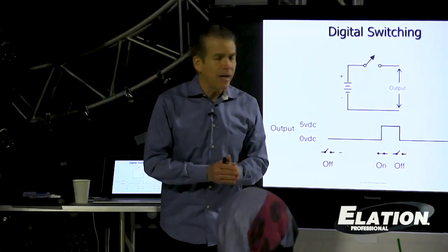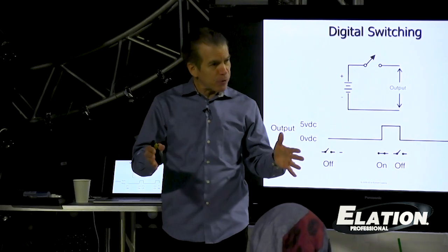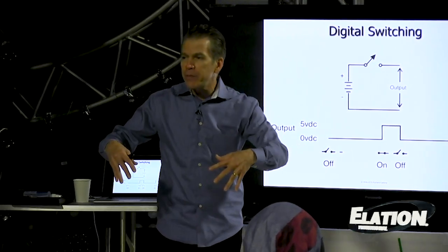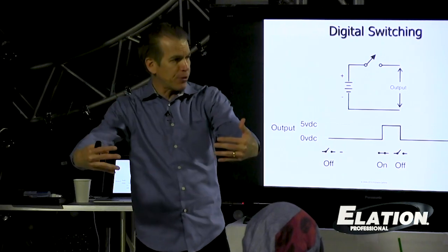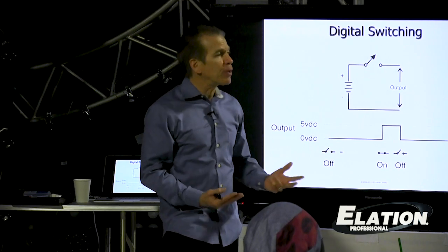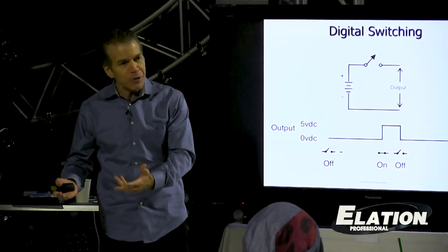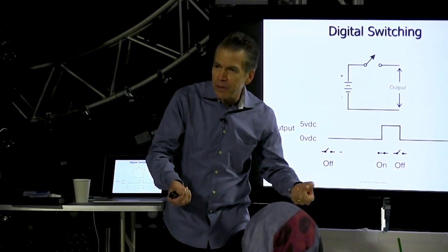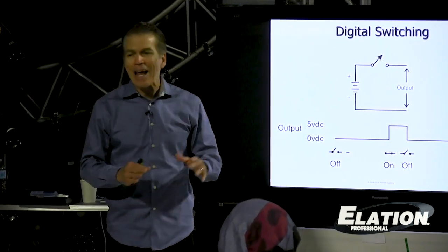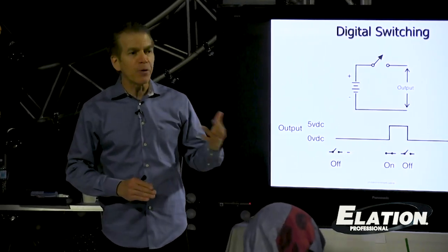If I had 8 batteries, 8 switches, 8 pairs of wires, and I gave Ray 8 voltmeters, then I could set the switches and transmit 8 bits at once. That's parallel transmission. Back in the 80s and 90s, there were parallel printers with parallel cables, and we don't use those anymore. Today, almost everything we do is serial data transmission.